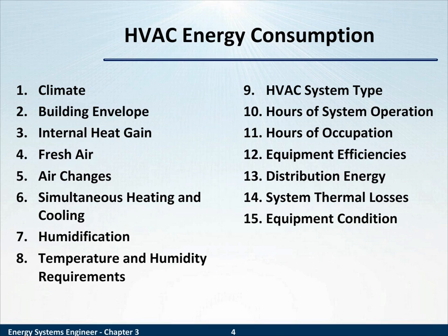Some of these considerations are, of course, external climate, the building envelope, and potential for leakage, as well as solar heat gain through glazing, internal heat gain, particularly process heat gain. Fresh air and air changes affect the energy consumption. Places where control systems have simultaneous heating and cooling, or heating, humidification, cooling.